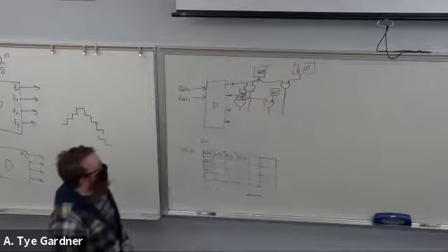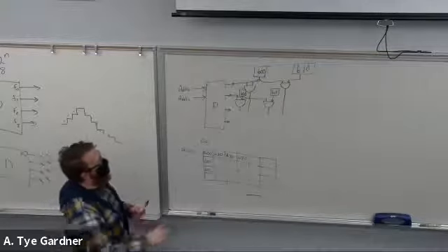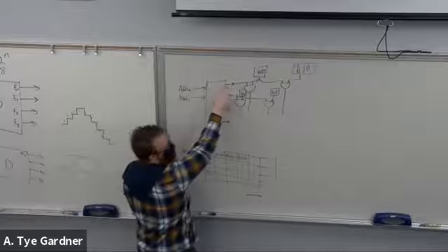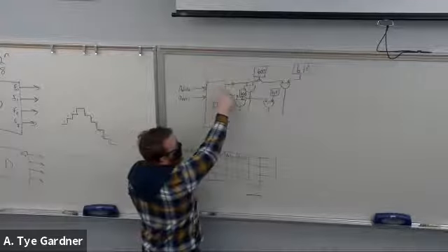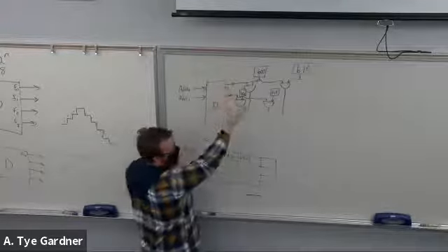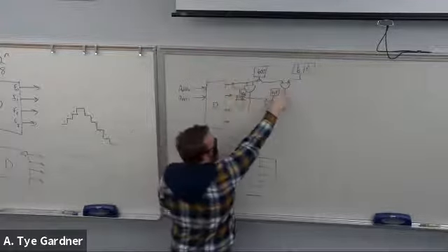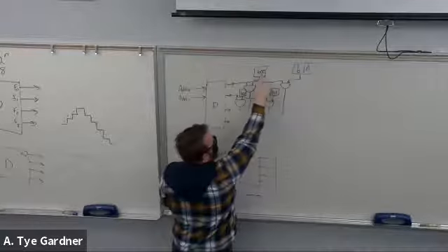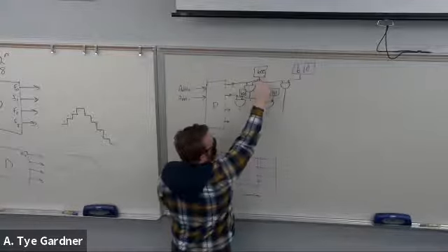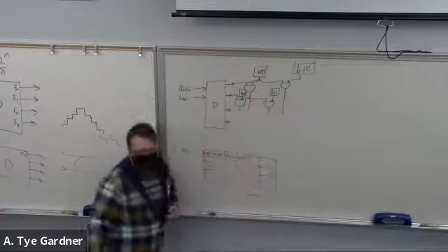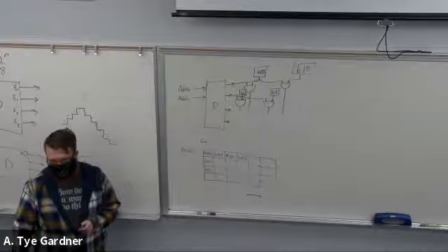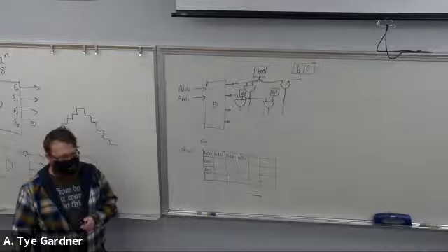Okay, so now all of those have that true. So if the address is 00, this line is hot, 1 hot. These two AND gates then output whatever the bit is in 00 and 10. Is everyone clear on that so far?